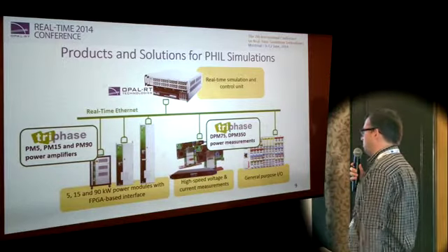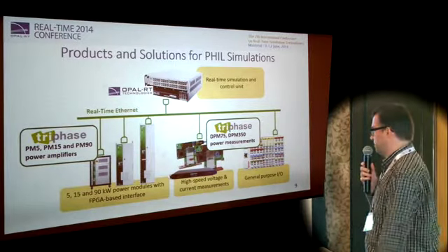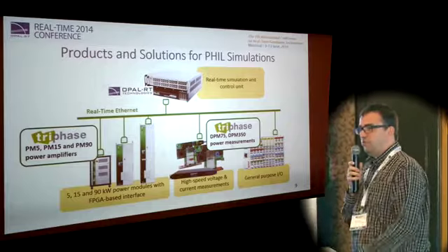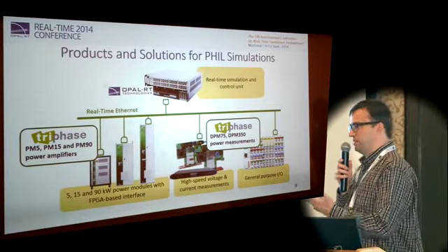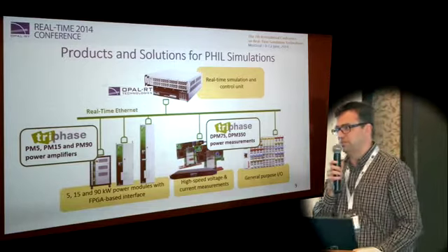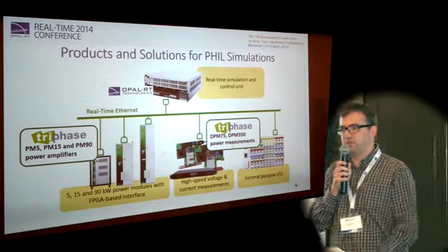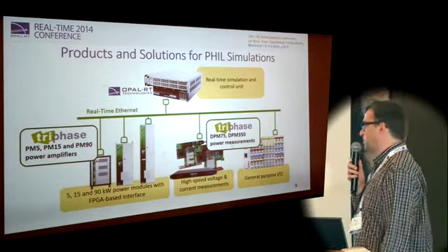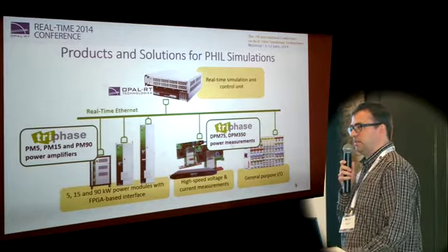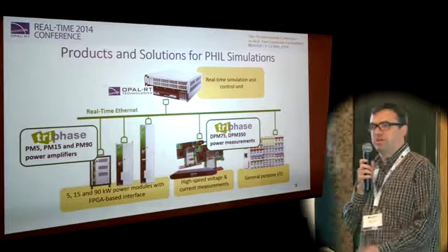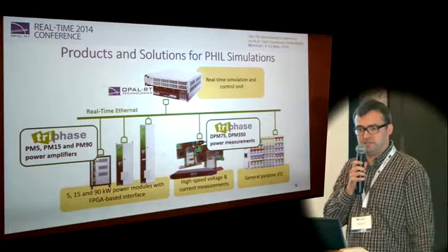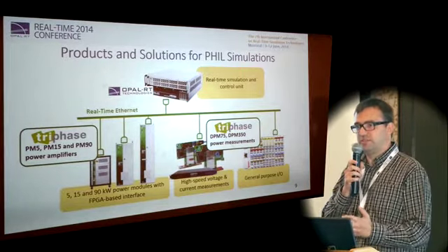And then you can use third-party hardware, for example, like the module shown on screen, for all your other needs like analog I/O, digital inputs and outputs, temperature measurements, getting, for example, a torque sensor inside. That's one of the advantages of using EtherCAT. You can really create a real-time data network for which a lot of equipment is already available. So it's quite easy to set up an entire system.